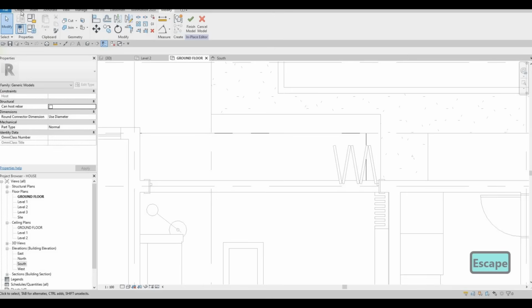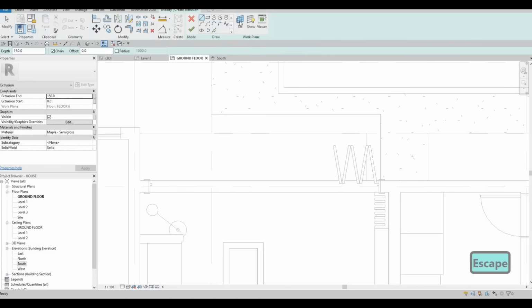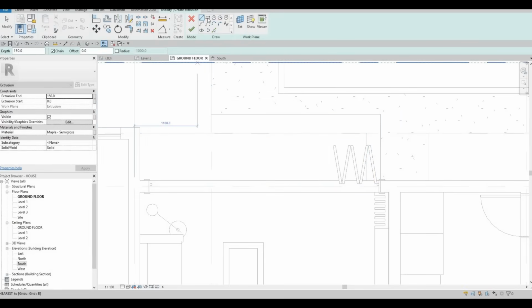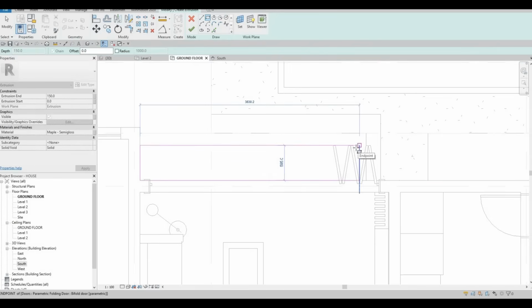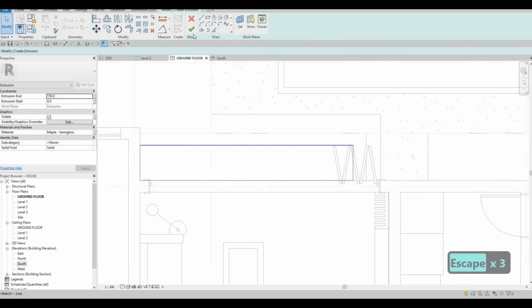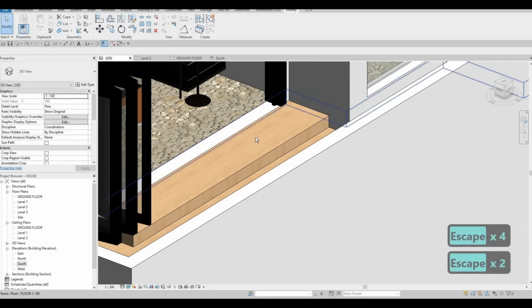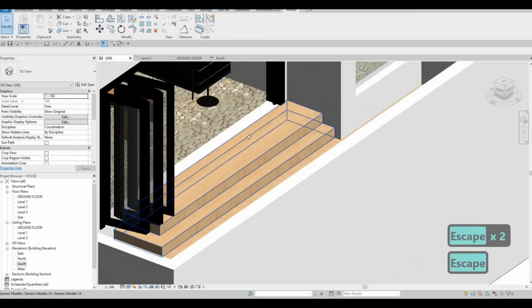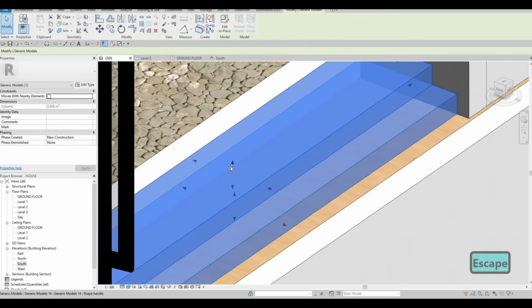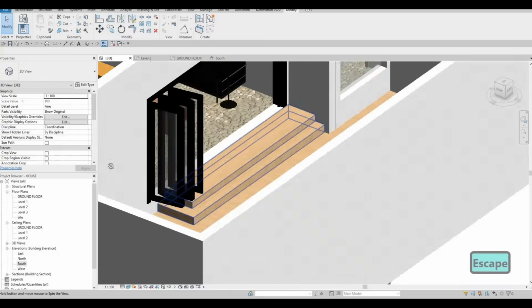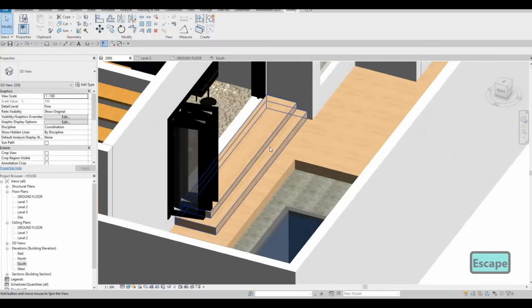We could add another one, create extrusion, set it, and then let's pick the plane which is right here, and then just add the one that is this one right here. I think the spacing looks good. I'm happy with it. And just like that, we could just pull it a little bit downwards like that against the trim.